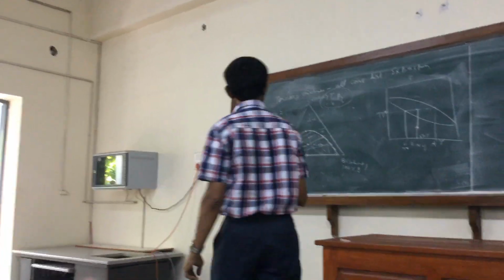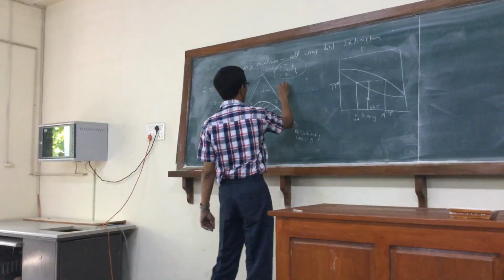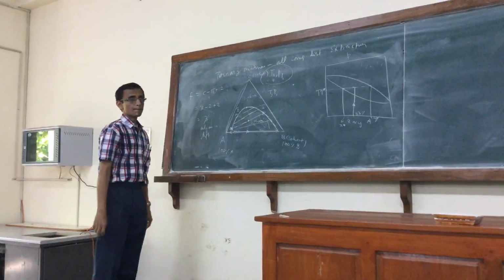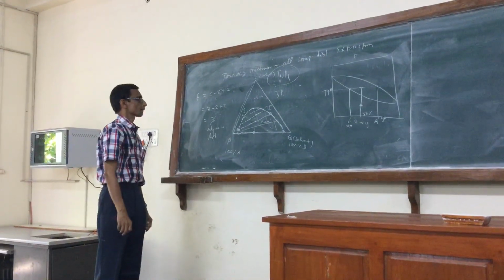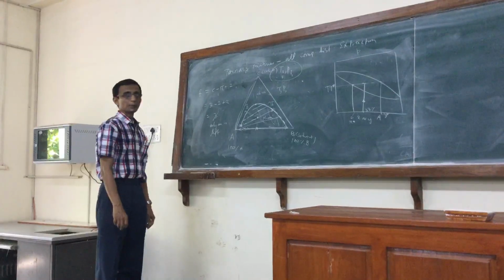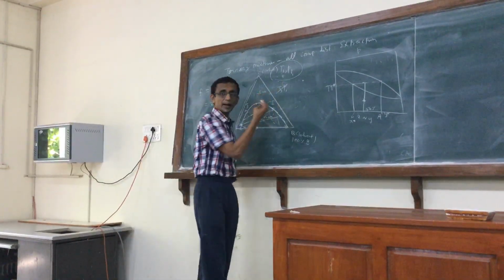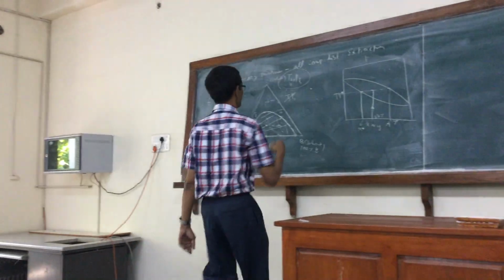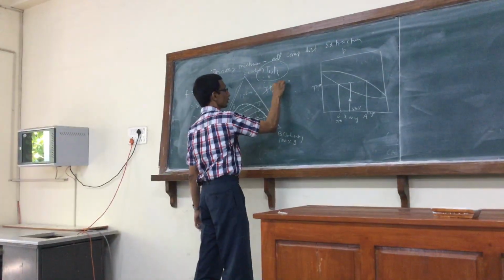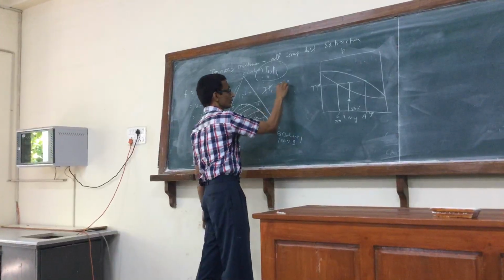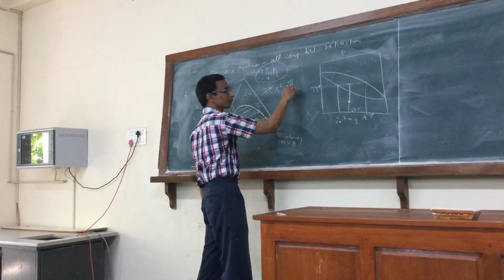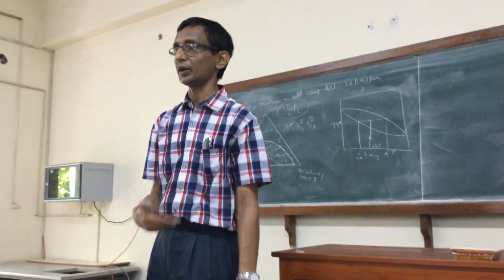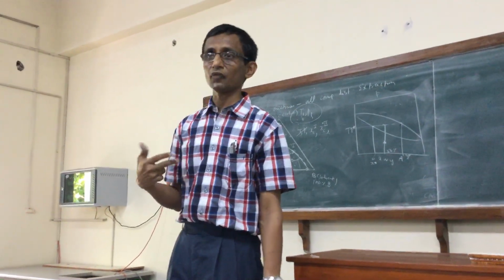Or let us say only 1 degree of freedom, so let's list out the variables: temperature, pressure, and anyway, what are the other variables? Two phases are there, 3 components. So one, the solute is first, XC1, that means the mole fraction or weight fraction of C in phase 1, and that of C in phase 2.